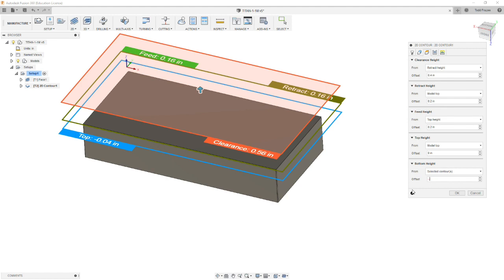So we're going to go 0.01. Our thickness tolerance is 0.005 or 5/1000ths of an inch. So if we leave 10/1000ths, we'll definitely fully clean up when we machine off the other face. If we don't, we know our part is too thick and out of spec, and will need to be reworked.